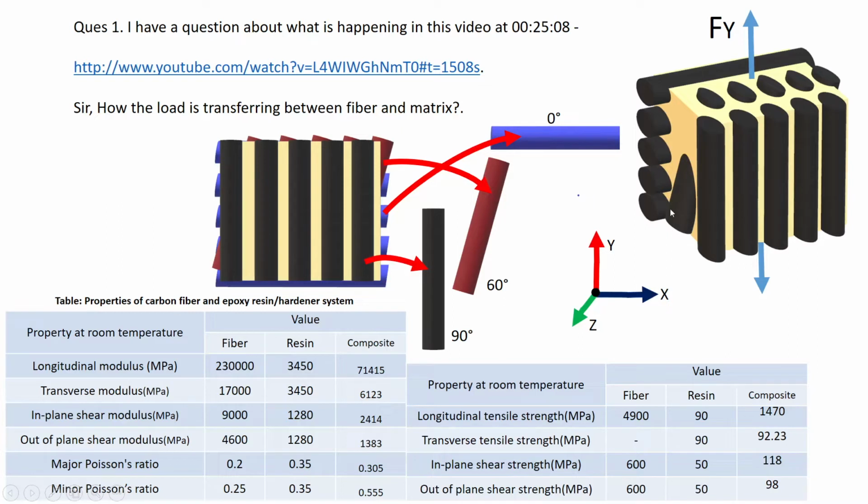So the sine theta components of all the fibers you are using would club up together to provide support equivalent to this force. Now you will have to figure out how many fiber layers or composite layers should be there in this entire composite so that the sine theta components of all these fibers, together, give the required support. The normal, longitudinal components of all these fibers give no contribution, as longitudinal strength is all in this direction, and then we'll stack composite layer after layer.